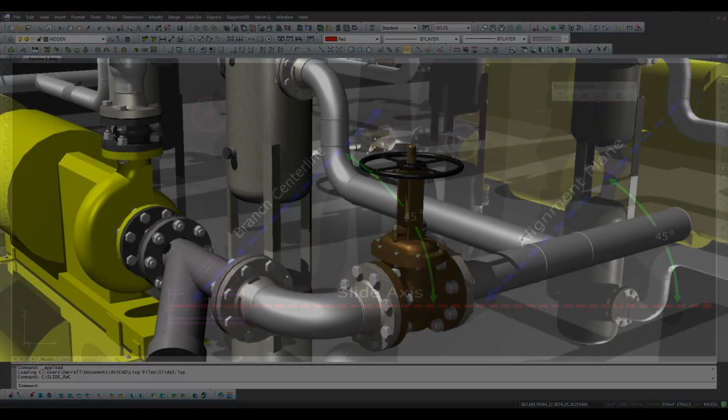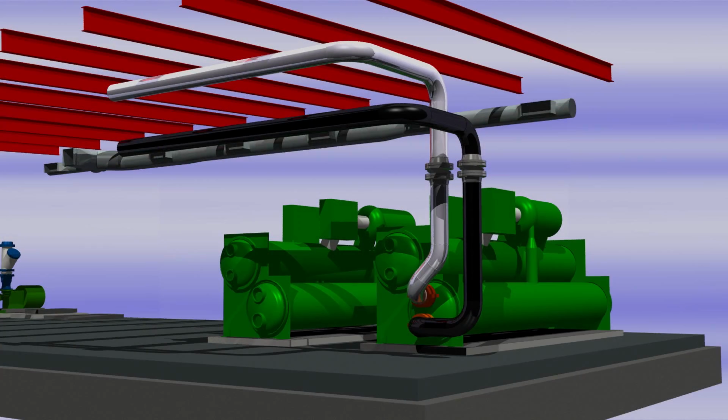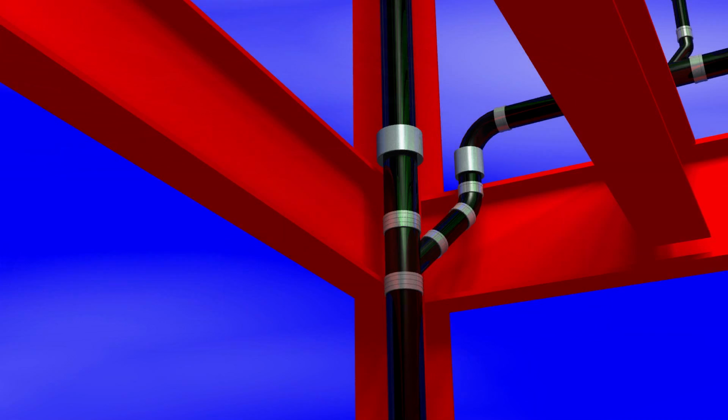We'll slide the T and an elbow on the supply manifold of this boiler skid. We'll also slide the diffuser in order to align its vent with the inlet of the expansion tank above. We'll install the chill water supply and return piping shown here on this chiller. Then we'll connect the waste riser to the lav header above. We'll use the slide routine and a 3D rotation command to set the elevation and rotation angle of the Y.